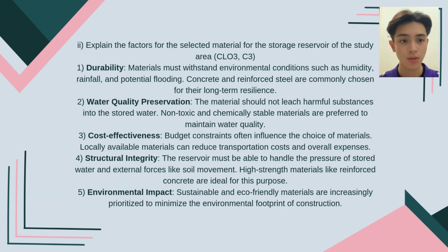For question 2, explain the factors of the selected material for the storage reservoir of the study area. First one is durability. Materials must withstand environmental conditions such as humidity, rainfall, and potential flooding. Concrete and reinforced steel are commonly chosen for their long-term resilience. Second one is water quality preservation.